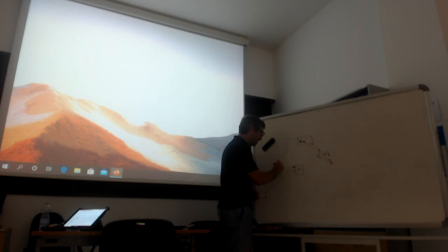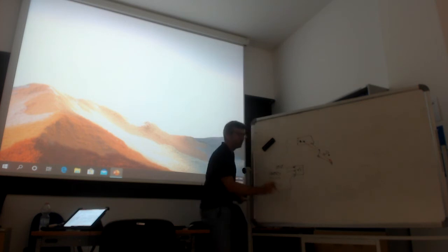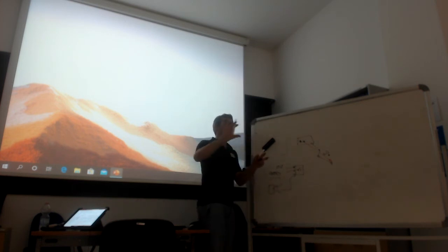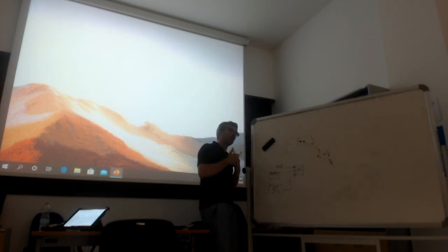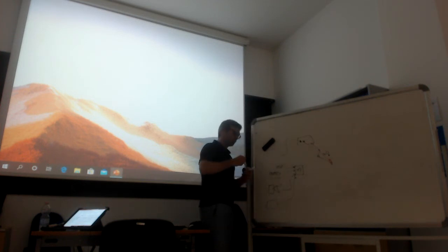Then, okay, IMU, odometry, the visual flow. So you have a camera, let's say, and you see features, and these features change from one frame to the other, and you know the motion from the feature, or how the feature moves. You know that you have moved. So this is visual flow. Then you have a LiDAR, which is a scan matcher. And normally you have a laser, and you use that to correct the position.